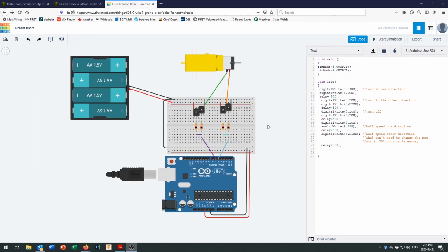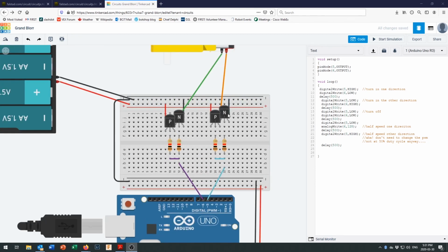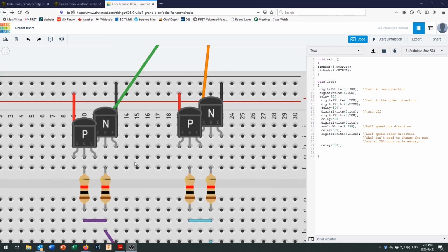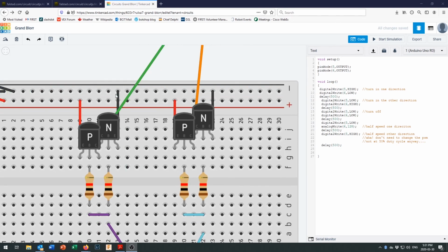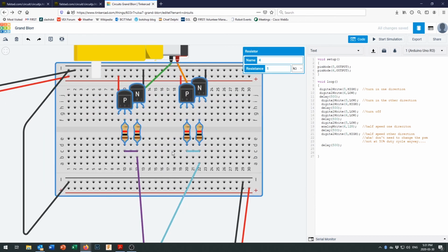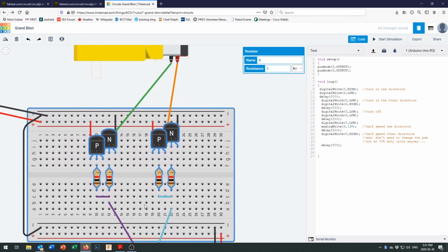And just like that, it's all done. An H-bridge, what do you know? Now, to be perfectly honest, I didn't get it on the first try. But I went back and I looked at my schematic from when we were talking about the H-bridge, and I said, okay, I've got the 2 collectors joined together here for my NPN and my PNP, and I've done that on both sides, forming that H. One side goes to high voltage, one side goes to low voltage, and the bases come out and through a resistor, they connect. I wanted to move the whole screen there, just a minute.